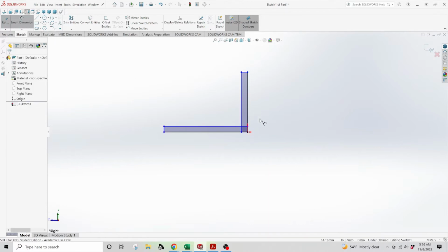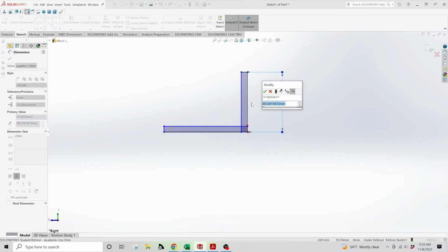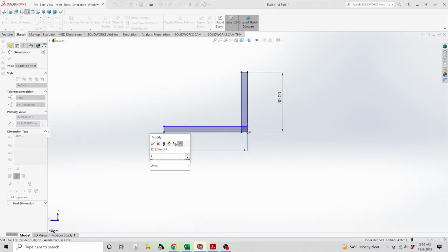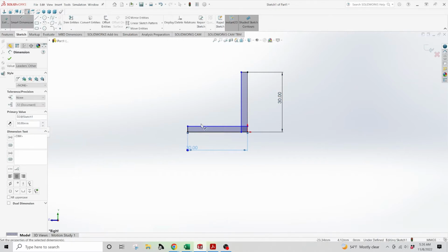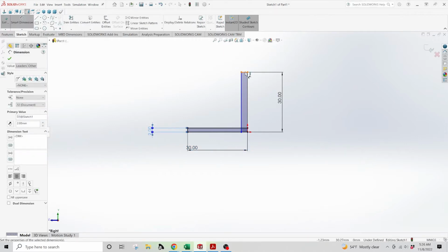It's a little hard when it's an L bracket, because you're split between one and another, but in this case we want to just make sure that we have the detail that we need. So this also needs to be 30 millimeters, so make sure again your unit scale is all correct. This thickness needs to be 2 millimeters. Same thing with this.